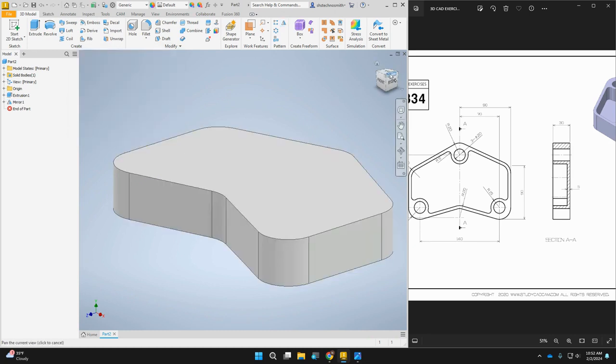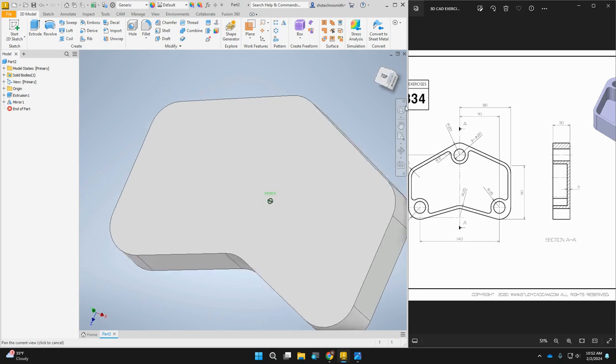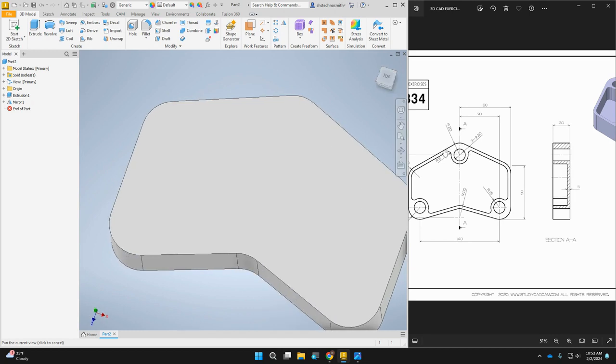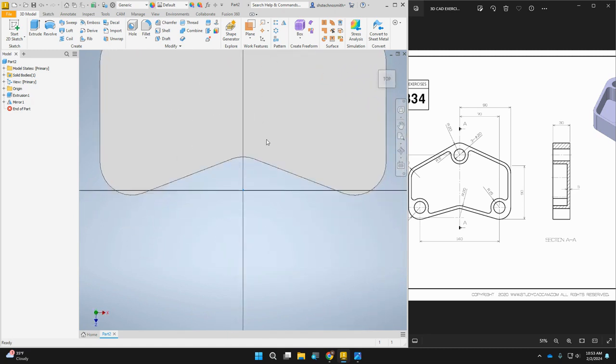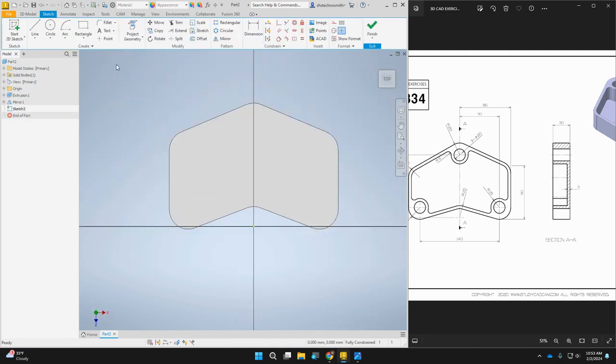Click OK. Now I'm going to add the circles in next. When I offset, I want to have all my features on there, and then I'm going to offset the whole thing. So we're going to create a new sketch here, and then we'll add 3 circles roughly where they're going to go. They're all the same size, 3 at a diameter of 20. So make them equal to each other. Dimension one of them to 20, and then we have to line them up.